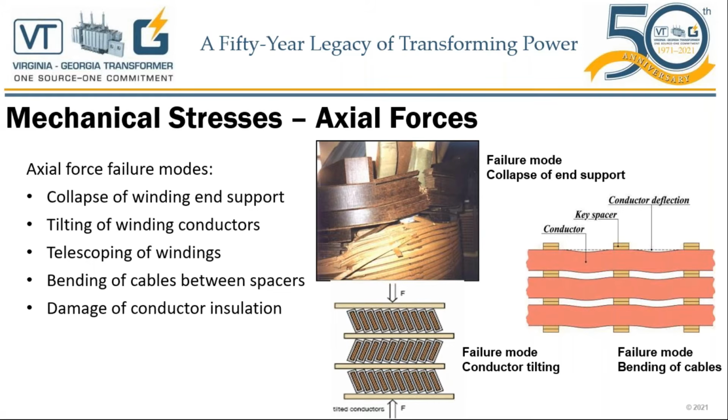It's basically that big, thick, special material ring that is used to keep the coils under pressure using the jacking mechanism that the manufacturer has. So that big, thick ring is used to distribute the mechanical force that keeps these coils under pressure.